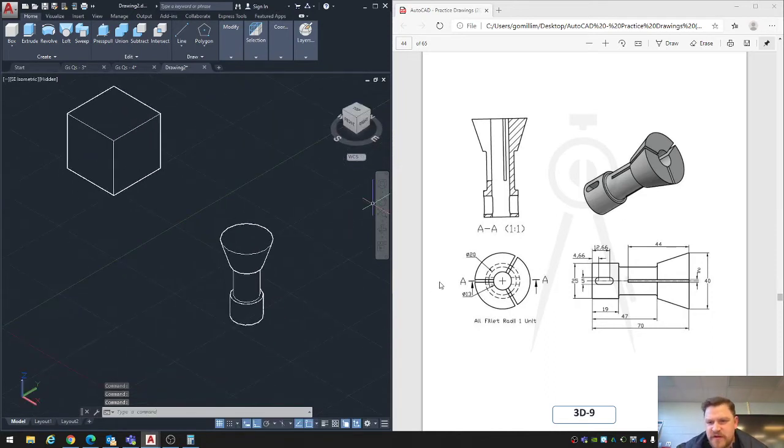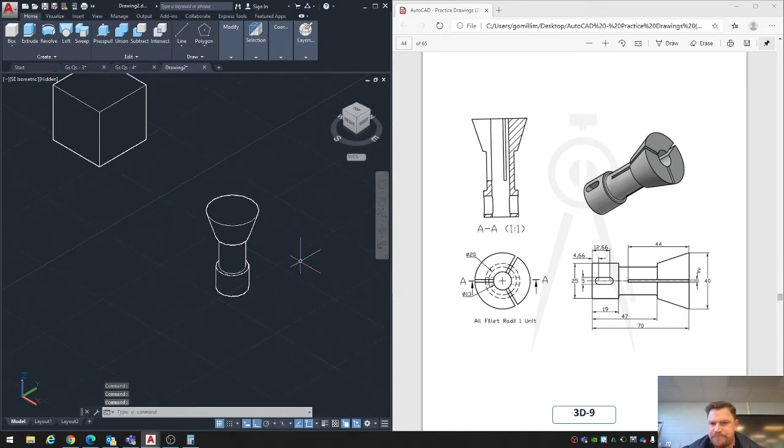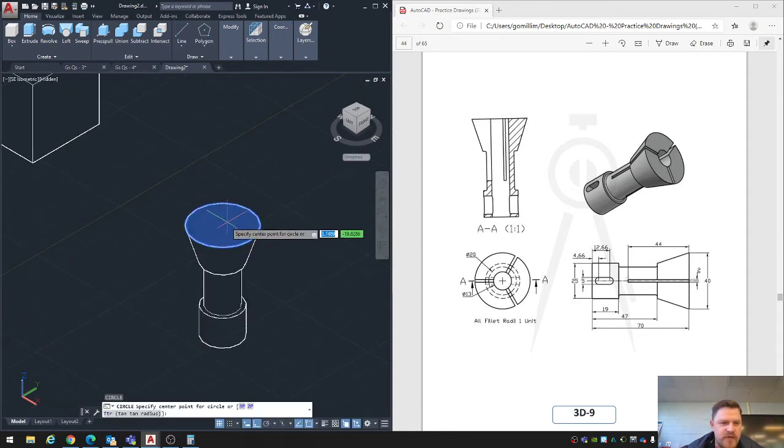Now I think I just have to cut all these other little pieces out, which might be a little tricky. Looks like I've got this little shape here and then this one up here. I think this goes all the way through. This circle that goes up top looks like it goes all the way through. So maybe we'll start there. It looks like the circle of that is a diameter of 13, so I'm just going to put a circle, hover, and then go there, diameter of 13.